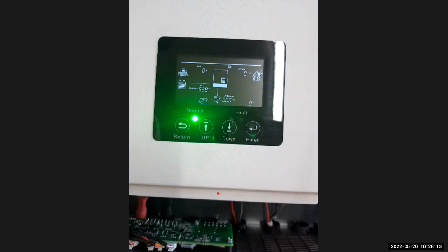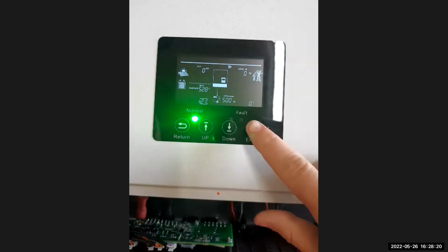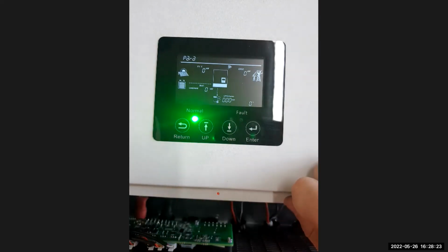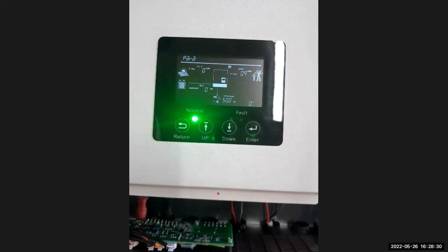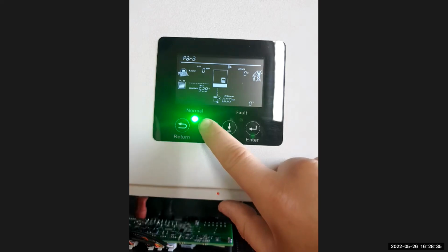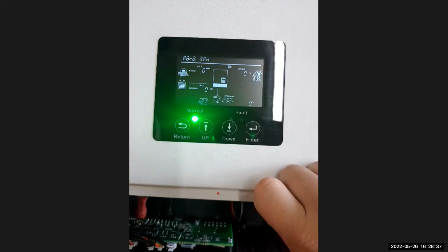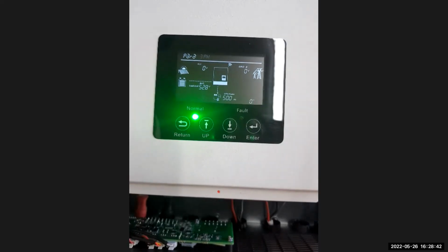Setting number 21 is where you are able to tell the machine the parallel mode. As I select setting 21, you'll see on the top hand corner there's a 1PH flashing. That tells the system it's a 1-phase parallel system. As soon as you press the up button, you'll see a number flashing for 3PA. That tells you it's a 3-phase parallel system.